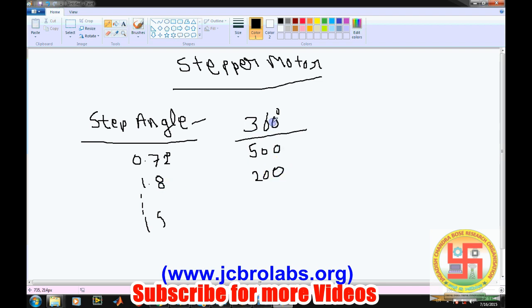This is very simple: just divide 360 by the step angle and it comes out to this number. And if it is 15, then we need simply 24 steps. So we talked about steps, we talked about step angle. Now the next thing we'll talk about is how to apply a step.